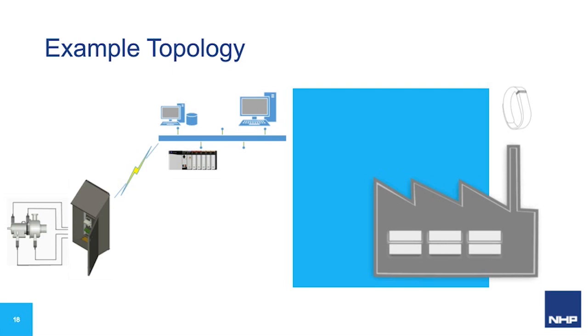So once we have the required FFT bands for each channel, the vibration values are there inside the PLC. And then once they're in the PLC, obviously we can start doing things like pushing them to historians or to SCADA screens. But what's also important to note over here, in parallel to that, we could also be logging that data. So when I say log the data, I'm referring to the raw time waveform.